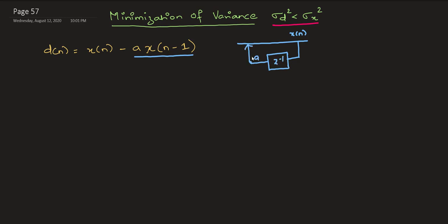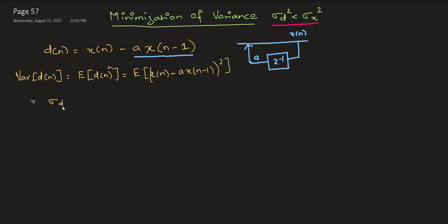There are two advantages for doing so. The first is that the constrained limit of Rxx1, the autocorrelation, from 0.5 to 1 is going to be made broader, to 0 to 1. That is the first condition that will be proven here. The second condition is that this can be scaled up. What if I want a quantizer which is not just using the difference of two successive samples, but a lot more samples? What if the difference is not just between two samples? It can happen, right?